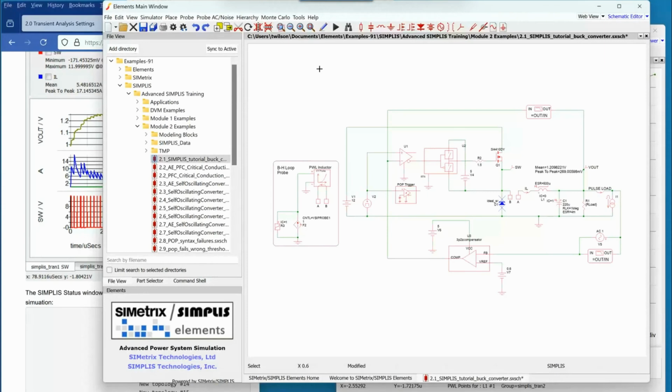Exactly. Well, there's one application, for instance, where it's important to have perhaps more segments. If you have a flyback converter with multiple outputs, and you regulate on one of the outputs, the theory tells you that you're going to reflect the other capacitance from the other windings, scaled by the turns ratio squared, to make a single output winding with all capacitors and resistors collected on the same point. And when you do that, you assume that the dynamic resistance of the diodes is almost equal to 0, which is no longer the case when you go into light load conditions.